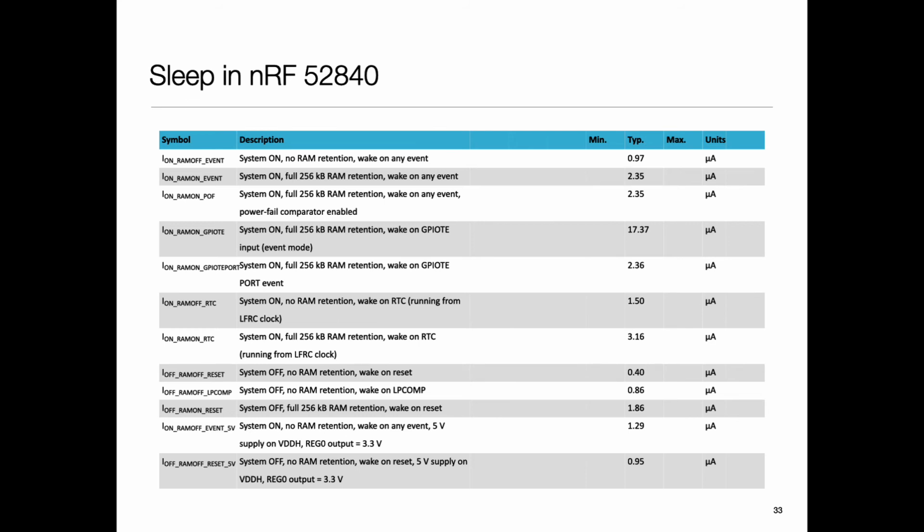So you see all these modes and the corresponding current requirements. Loosely speaking, the deeper in sleep you go, the harder it is to come out of it, the more you will save while you are in that mode, and quite possibly you will forget more. So these are the three very loose trade-offs.